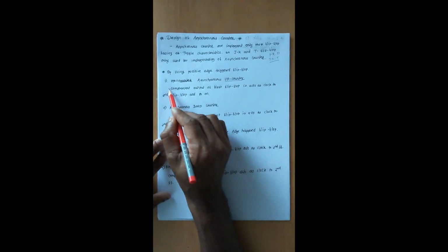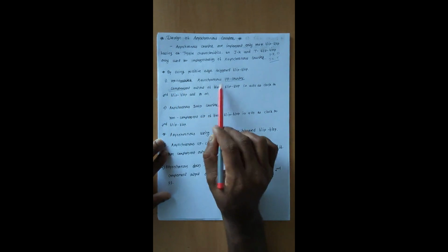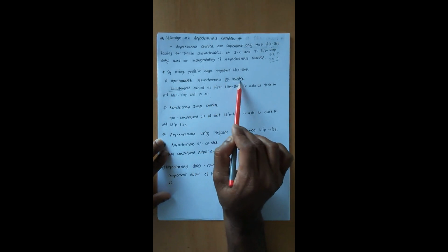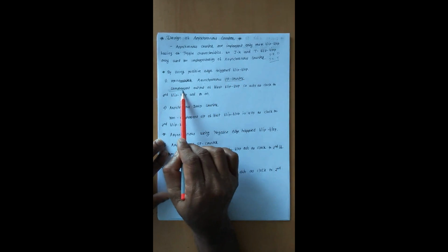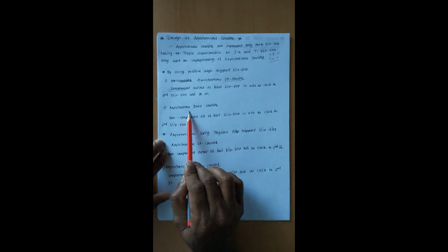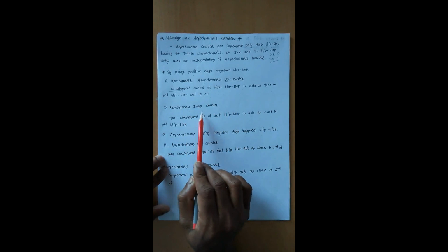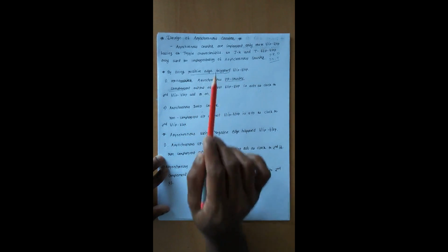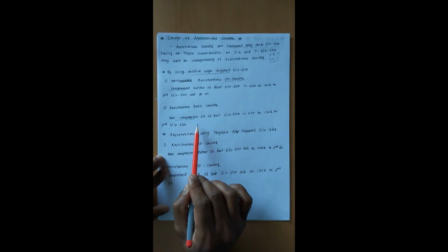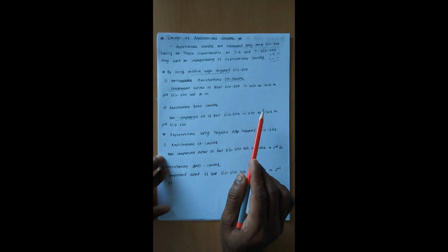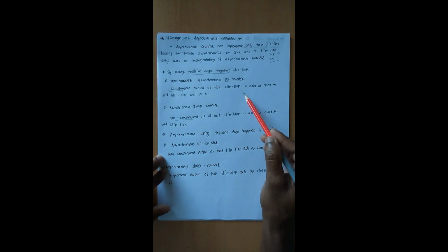This point is to be considered because we are implementing a positive edge triggered asynchronous up counter. For the implementation of an asynchronous down counter with the same positive edge triggered flip-flops, the non-complement output of the first acts as a clock to the second flip-flop. This is the minor change between the up counter and down counter.